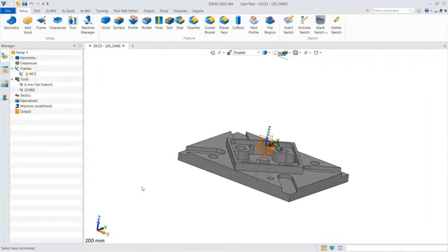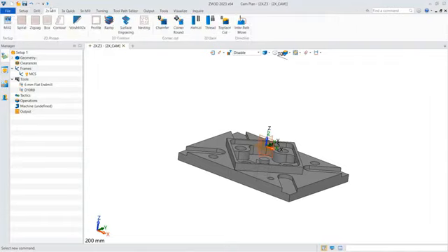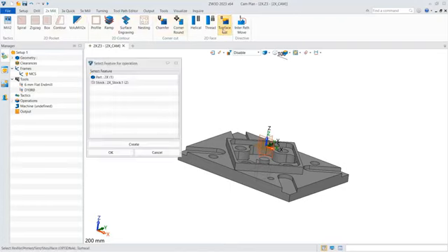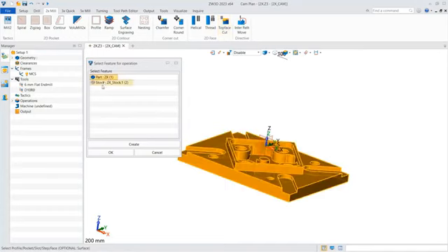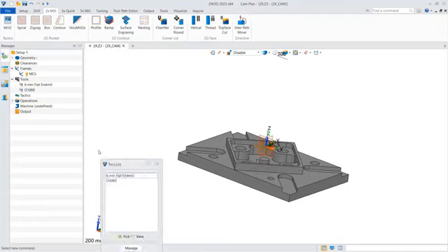Finally, let's start to create the toolpath. For the roughing, first we choose the top face cut operation to remove the excess material. This operation can also finish the top face of the stock if there's no excess material to be cut. Just select the part and stock as the feature, and D10 as the tool.